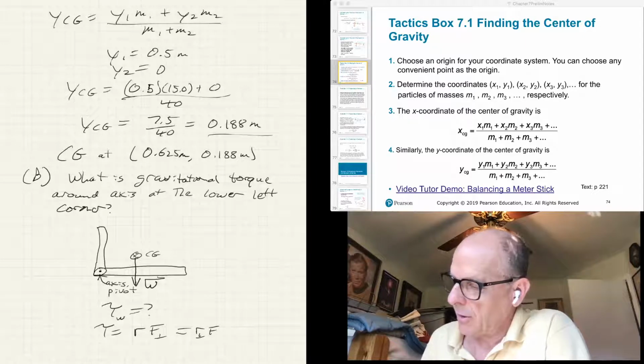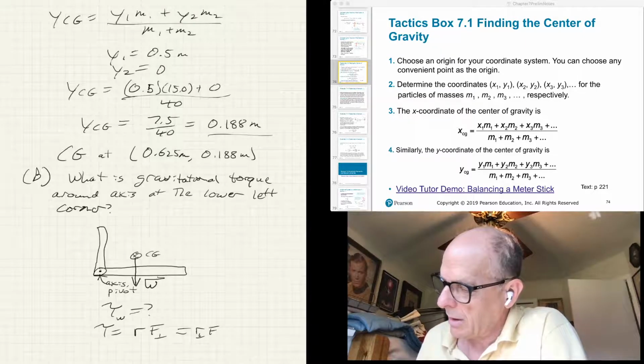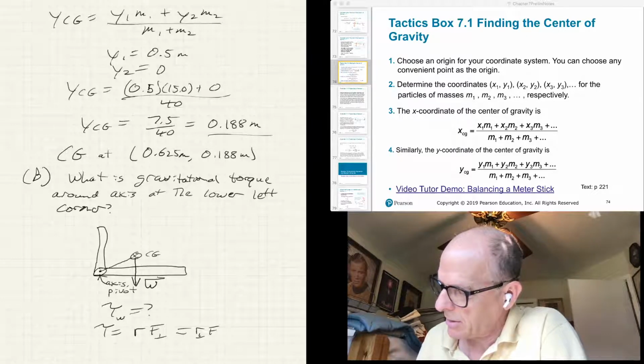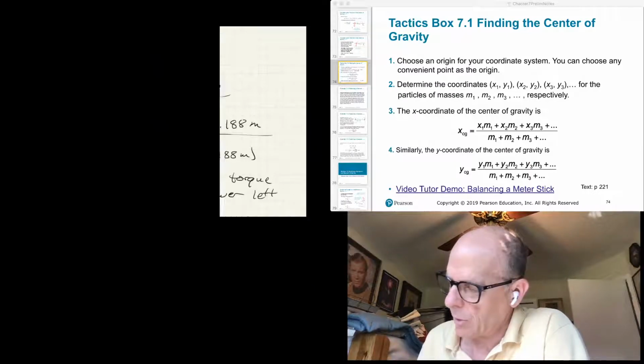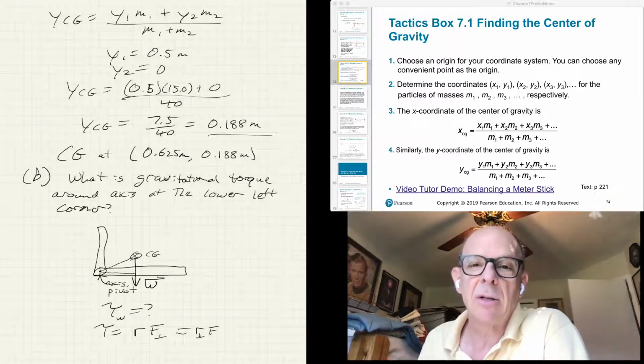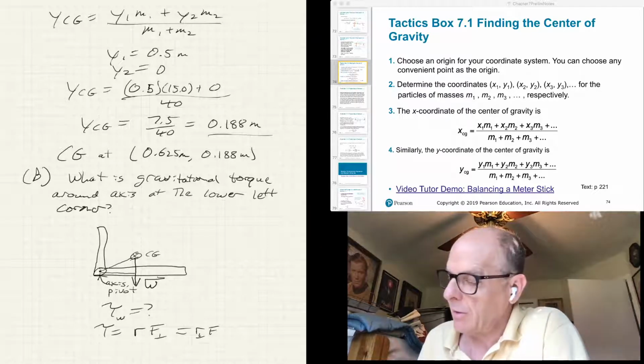And so for this particular one, I think the easiest way to calculate that force, we can draw r is this distance, and then I would need to calculate the component of the force that's perpendicular to r, but it's easier to just calculate the total force times the perpendicular distance from that force line to the axis.